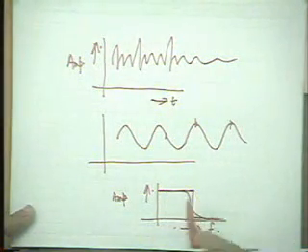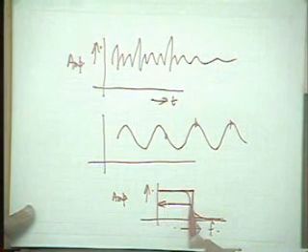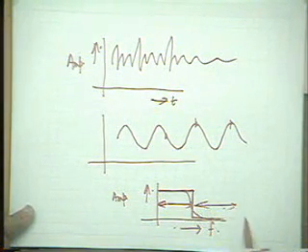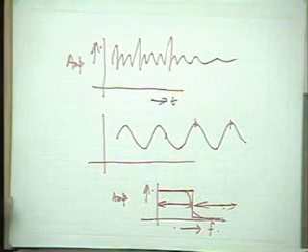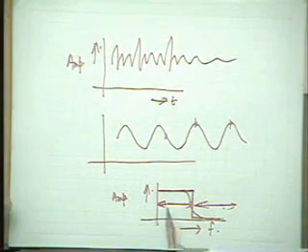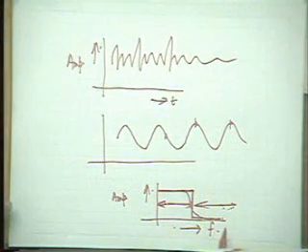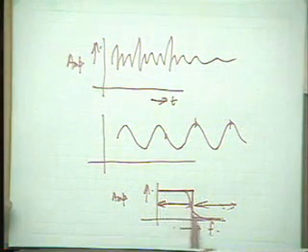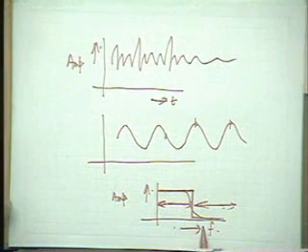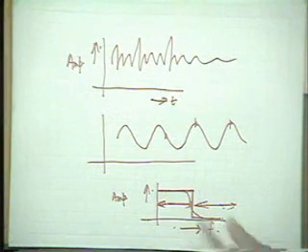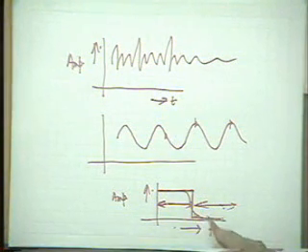That is to say, this band we call the pass band, and away from the pass band we have a stop band. Really speaking, the pass band characteristic will not be as uniform as the ideal. There will be some droop here, and even in the stop band, where we ideally want an absolute cutoff, there will be some components which will be passed.